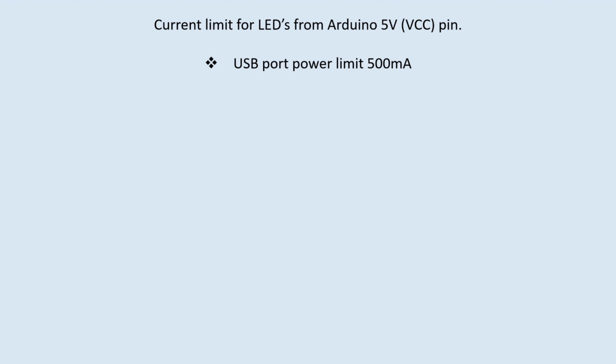So you get rid of that overhead. If you've got maybe only a couple of 100 milliamps available, well, the output from the 9685, because of the resistors that are on it, limits the output to about 10 milliamps. It's plenty enough. The LEDs light up bright. They're full brightness. They're good. But at 10 milliamps, you figure even at 200 milliamps available from the port, you can do maybe about 20 LEDs, but that's about it.